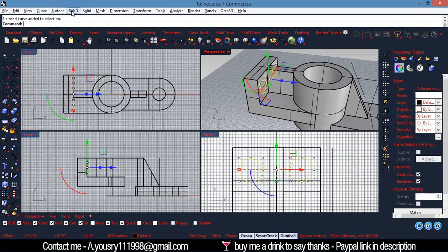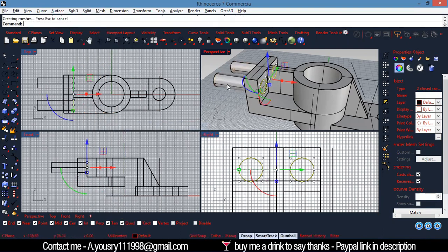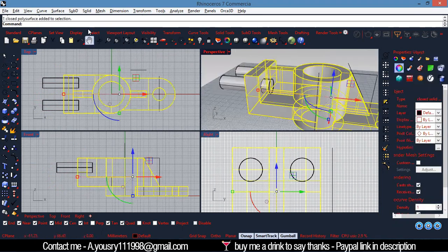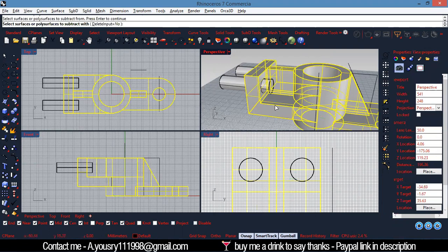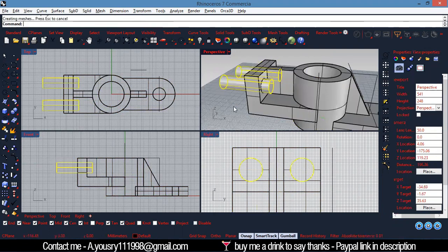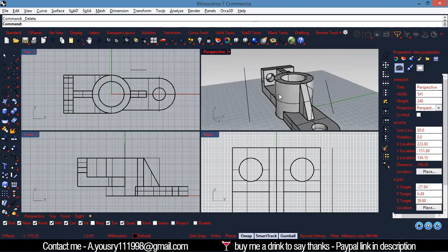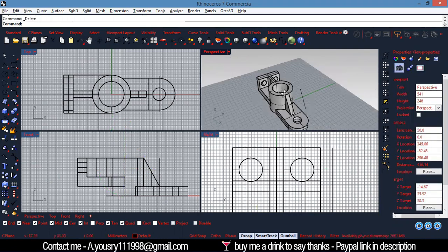Go to solid, extrude. Okay, and then slide a little bit, and then pick that Boolean difference. Boolean difference. So the surface here, and then those two. I'm going to delete both of them, and here we go. I have here my pot.